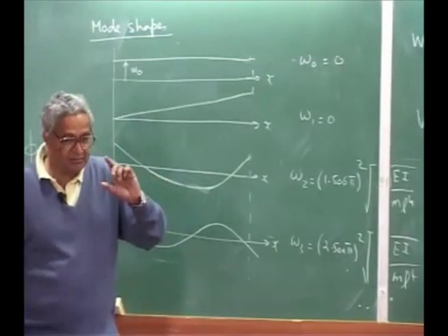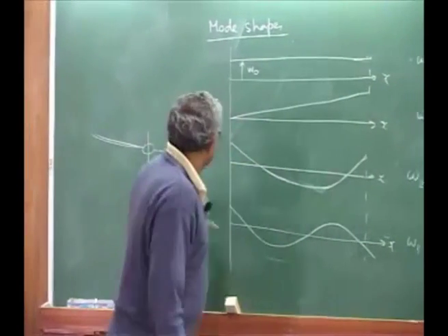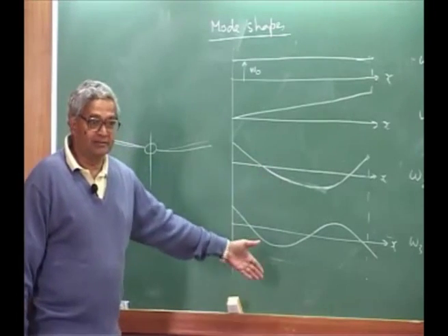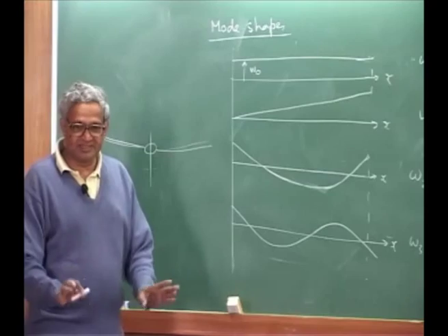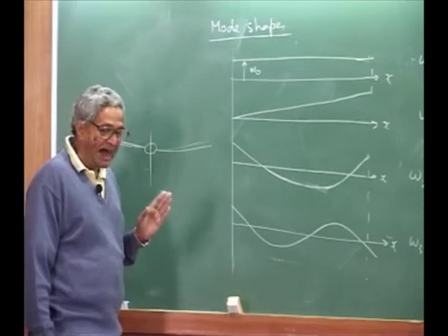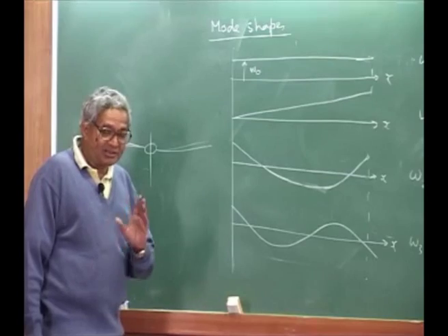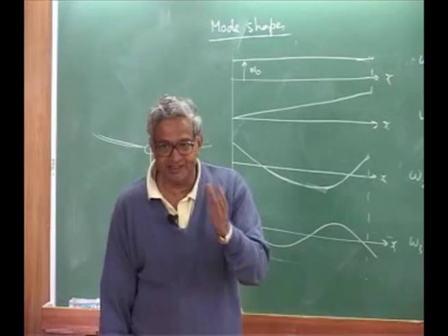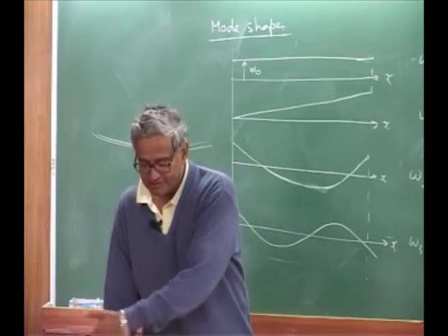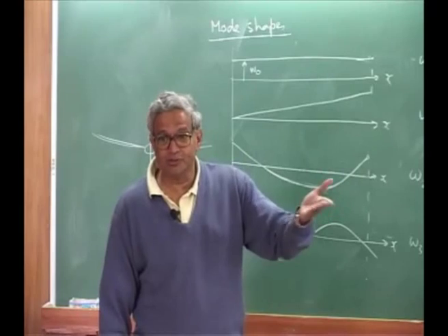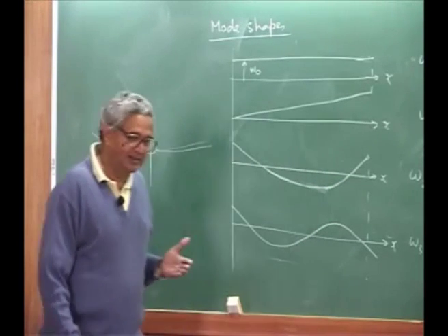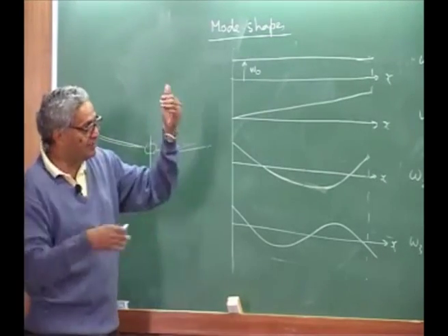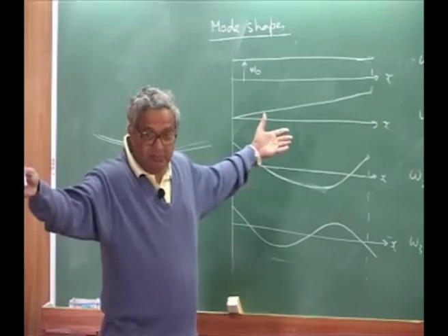So that is how you have to be very careful what I allow. Whereas if you solve full problem as it is, you will have everything without any problem. Because this is just to indicate that if you take half the problem, you have to be very careful about what boundary condition you are setting in that one end. Because that will give you only that set of solution. It will not give you the other solution. Okay, that is the reason why, to avoid that confusion, I solved the full case. In the sense, I said ML0, and that is the full free beam.